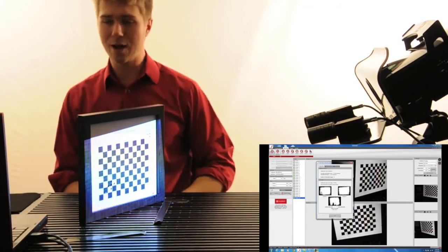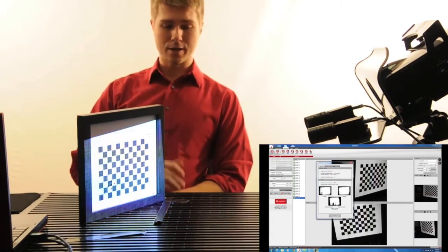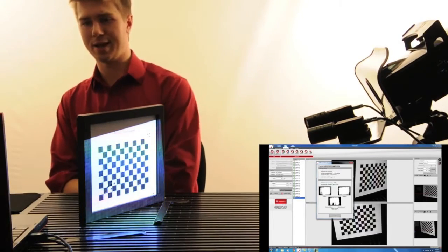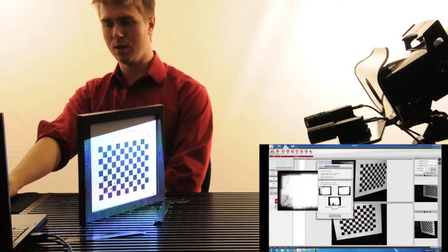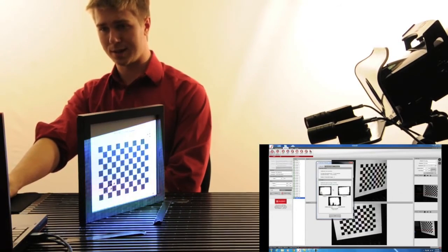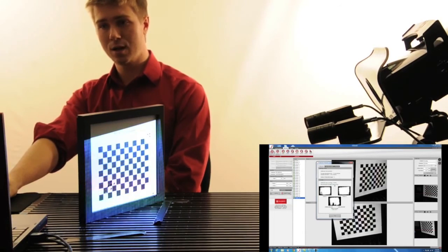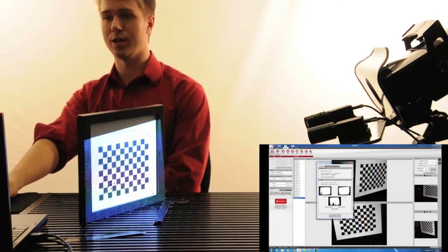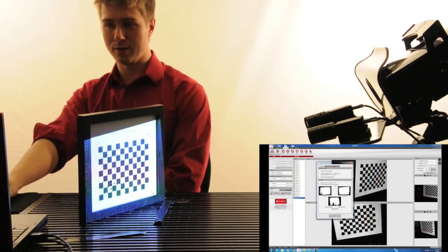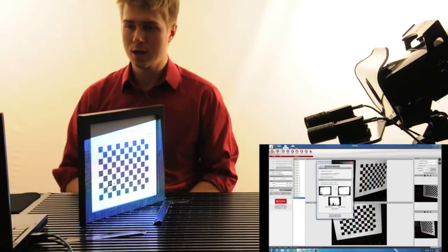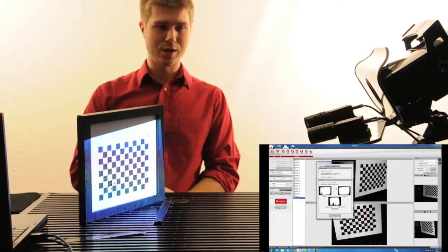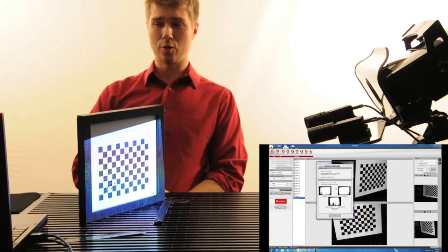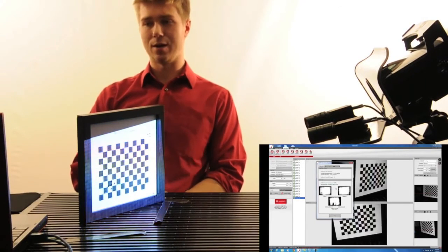Okay, so now we've gone ahead and done our calibration, and we can see the results of that calibration. Once we press calibrate, we'll get this little window that'll pop up after it does its processing, giving us our calibration space coverage, our standard deviation, and our average rejection error. So the recommended calibration space coverage on the software is above 65%. I generally recommend above 80 or 85. Anywhere 85 and up is a very nice calibration for the coverage.